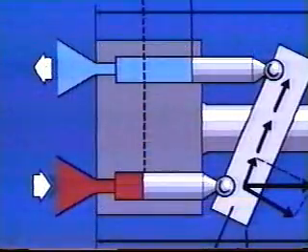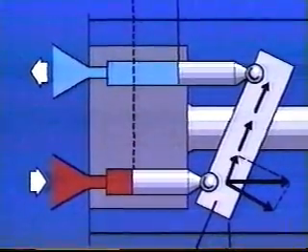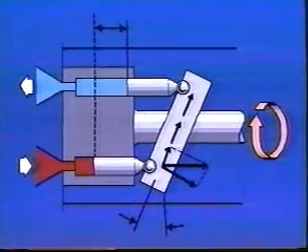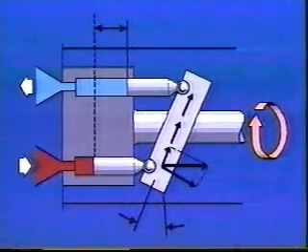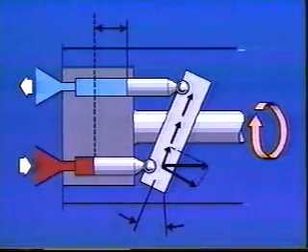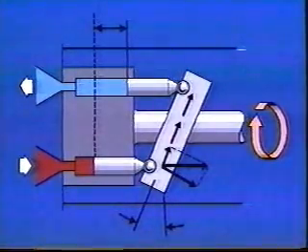A piston motor is almost identical in construction to a pump. The operation, however, is quite different. In a pump, the shaft drives the cylinder block, causing the pistons to move in and out of their bores, taking in and then discharging fluids.